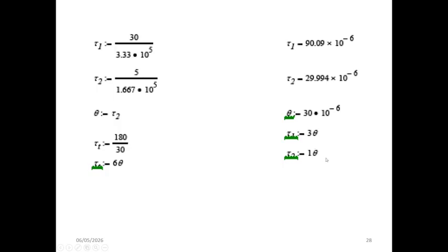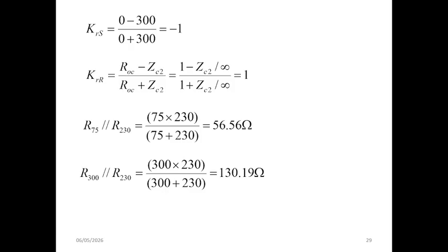This normalization process is very useful in lattice diagram analysis, as it allows the tracking of incident, reflected, and transmitted waves at discrete time intervals. It simplifies the visualization of wave interactions at different junctions and helps in systematically determining the accumulation of overvoltages at the bus bars.